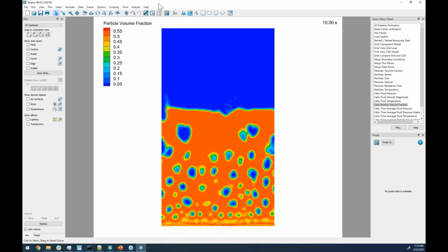We have a lot of Lego bricks that you can use to develop a workflow. In coming up with this webinar, Sam and I were talking about Tecplot, and it's like there's no bubble analysis button. So we're like, man, it's like Legos, right? You can use the value blanking feature, the extract blank zone feature, the integration feature, and you can chain all of these together, and you can build a tool like you would build a Lego model. So I'll use that analogy a bit today.